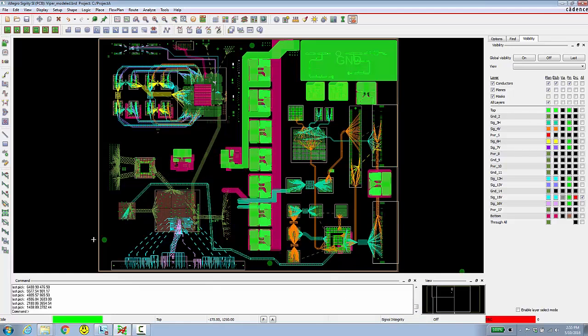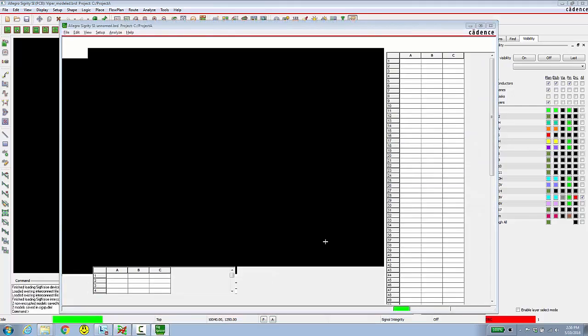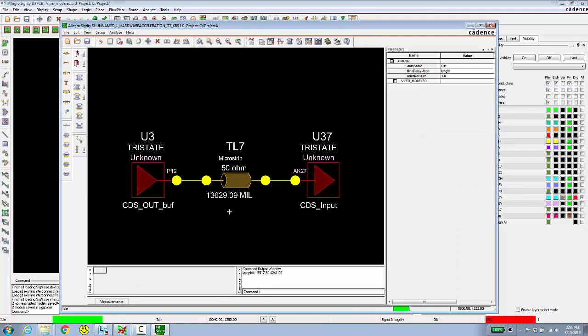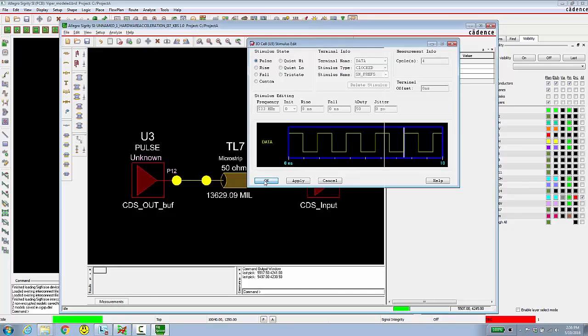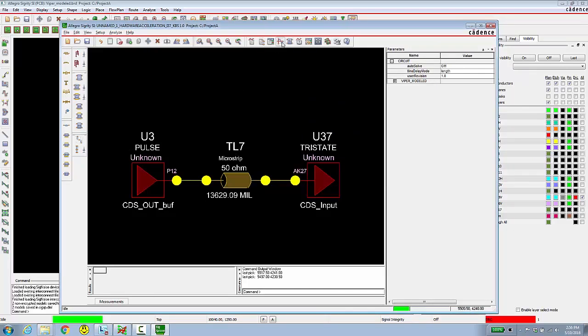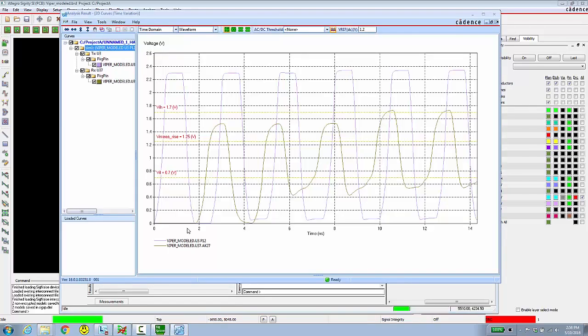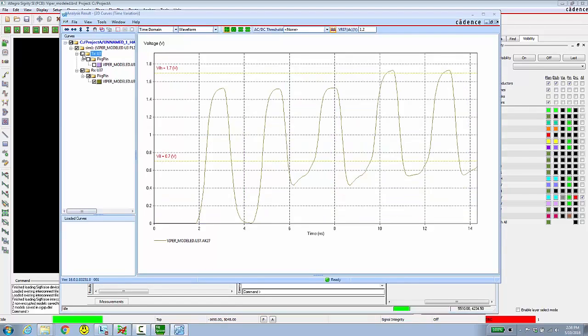Let's look at the result of what we did. If I extract one of the nets of the bundle to Signal Explorer, we will see a single T-line model representing the net. We've increased the length by more than 3 inches. Is this okay? We can go back and simulate in the design, or we can just as easily simulate here. Now would be a good time to see if we need a stronger driver to handle the length and loading. Even worse would be if this problem was not evident with the original 10-inch Manhattan distance.